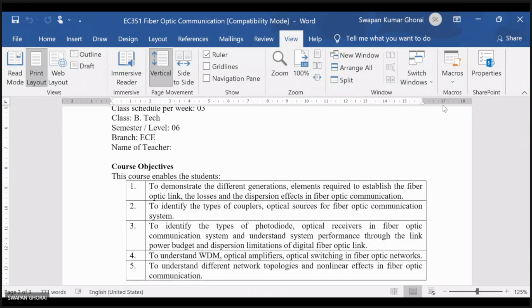Apart from photodiodes, some other devices are also there, but we will focus on photodiodes, because these are the fast devices. When you consider extremely high bit rate systems, other devices will not be compatible. Other devices like photoconductors and photomultipliers can also be used for detection of light, but photodiodes are the fastest device. That's why these are used for communication systems. So we'll see different types of photodiodes, like the pin photodiode and the avalanche photodiode.